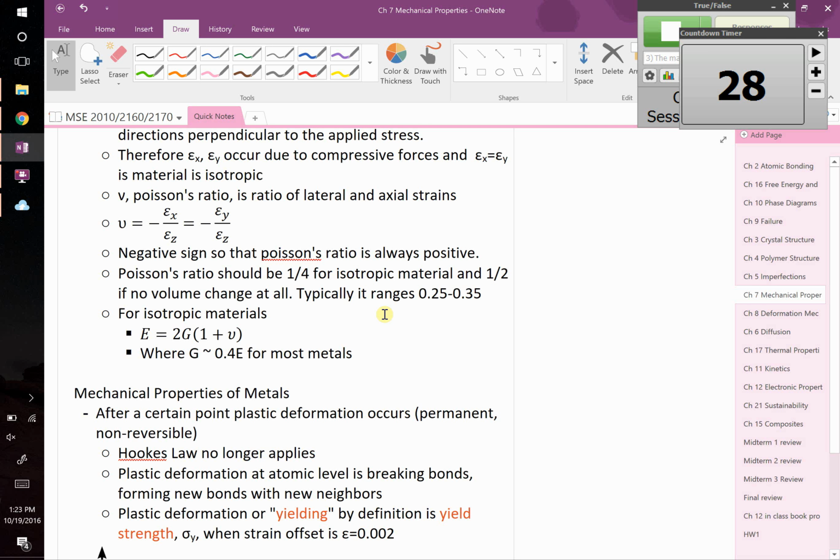Yeah, Matt? If you put any sort of force on it, it'll break. It would. If you pull it apart, it breaks easy. Let's talk about compression. If I compress cork, if it has a Poisson's ratio of 0, that means as I squish it down, it's not getting any fatter. Why?